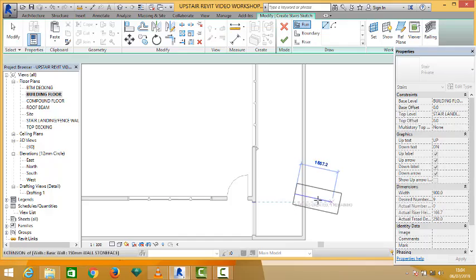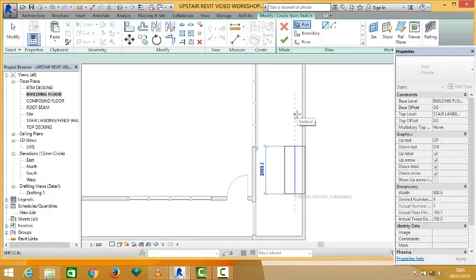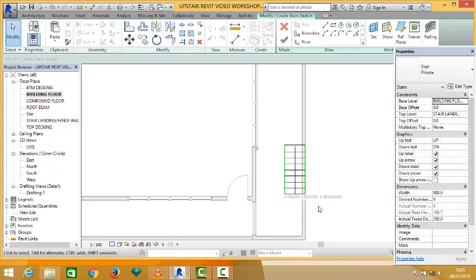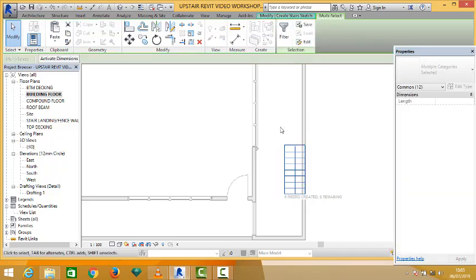Okay, if you look at this, you see 9 stairs, 9 risers created, 0 remaining. So we've gotten all of our 9 risers. Okay, so I click to place my staircase. Now you take note that the stair is entering into the wall, so I can highlight and bring it out. Fine, so it's out of the wall. I can also push up a little.